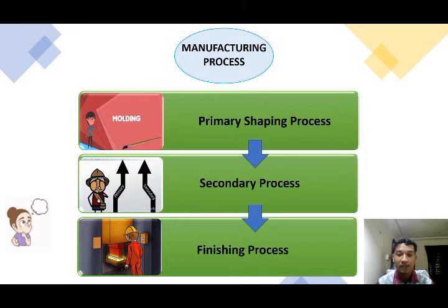This includes a shell of hydrocarbon or other appropriate gas. This expansion of the thermoplastic shell results in an increased volume and reduced density of the material of the outer layer. This can be controlled to provide an earplug having a sound attenuation portion and a stem portion, exhibiting a desired shape, density, hardness, and other desired characteristics. For the finishing process, the earplug is subsequently cooled and ejected from the mold. The finished earplug includes a sound attenuation portion, which is formed by the shape of the first cavity of the mold, and a stem portion, which is formed by the shape of the second cavity of the mold.